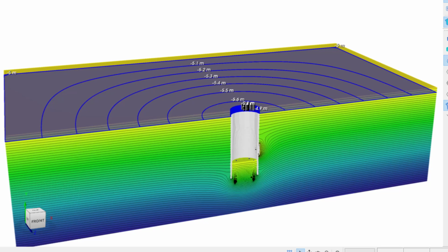As expected, the underground structures lead to a small, but nonetheless significant, 0.6 meter drop in water table elevation. Once this is stated, however, it should be noted that the analyses did not account for surface recharge.